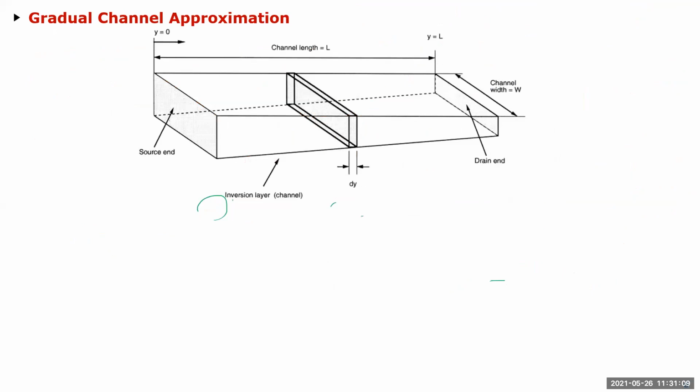And so what I've shown here is I have taken just that channel which is formed, the inversion layer, and I'm showing it as a three-dimensional structure to derive that IDS-VDS equation. And like I said, the height is showing you the charge density. In reality, there is no height. It's still a sheet charge, just to show you visually.